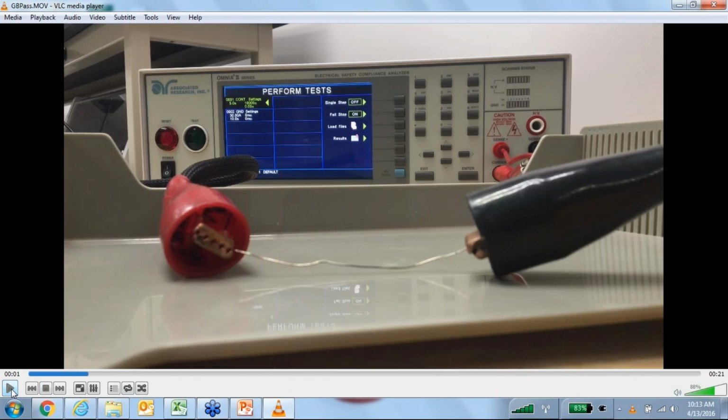So here we have a normal wire that you would use in your ground circuit. Okay, we have our 4-wire Kelvin connection. First I'm going to run a continuity test, which you would assume will pass because it's a wire. I can see there's no breaks on it, and it's a complete loop. And then after that, we're going to run a ground bond test at about 30 amps. I think most people probably run theirs at 10 to 15. 30 is a bit high, but we do go up to 40 amps for special industries and special applications. So let me let this run.